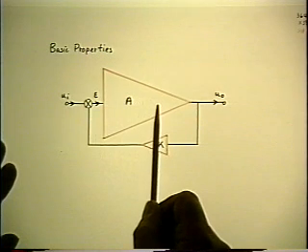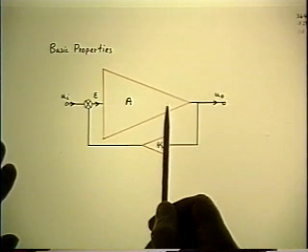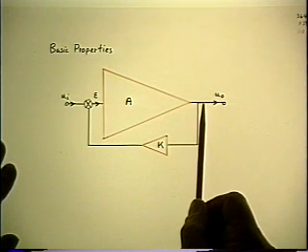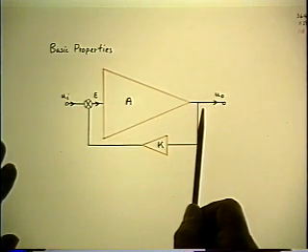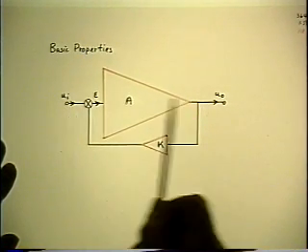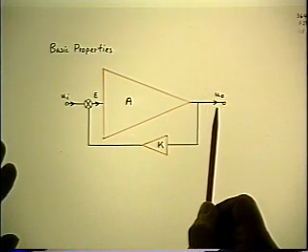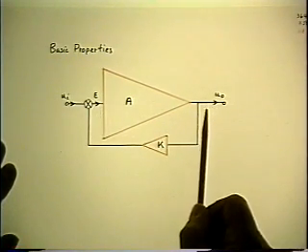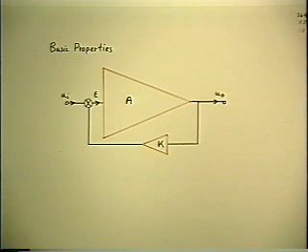So the amplifier now has an input that contains attenuated reversed phase harmonics. So it amplifies the reversed phased harmonics, so the new distortion that comes in is partially cancelled, because the phase is opposite. And so in the output, you don't get the ideal perfect result of no distortion, but you get a much reduced distortion. And it's self-adjusting, because whatever is not cancelled out gets to be fed back and re-amplified. It's the reversal of phase that causes the partial cancellation. So he had to iterate the solution to his problem to get the answer that finally worked.